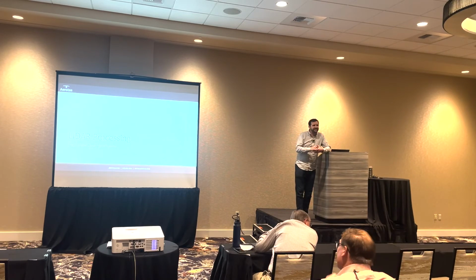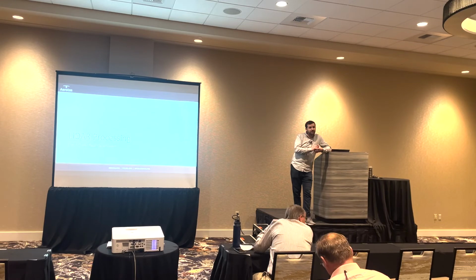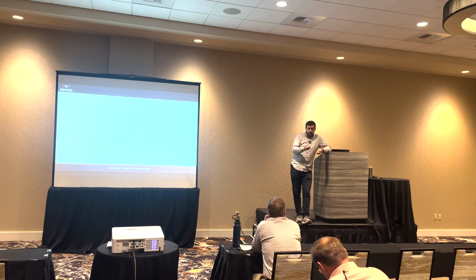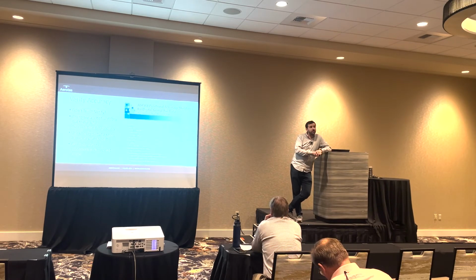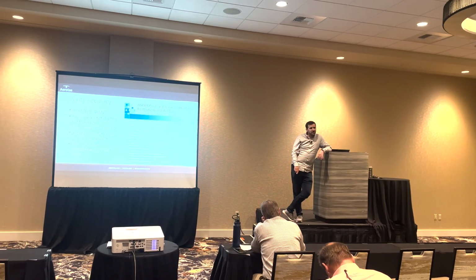Later on, are you going to talk about vertical terrain accuracy checkpoints too? No, I wasn't, but I can talk about that for a minute. Yeah, because there is the accuracy of your raw data, the positioning of the drone, and how accurate the lidar is at good distances. But at the end of the day, you're modeling the surface, right? And all models are wrong, but some are useful, and you want to know how useful your model is. So do you incorporate vertical terrain accuracy checkpoints?